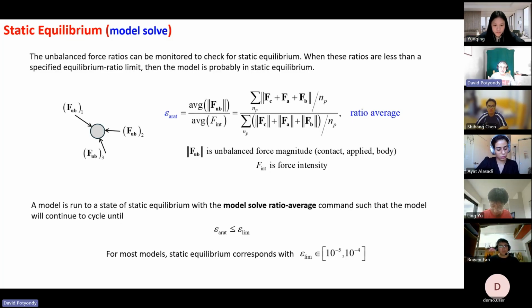And so one of the ways of determining that is just to cycle for a huge number of cycles, and eventually you're going to see that all the velocities are incredibly small, like 1 × 10^-12, because they're just vibrating at this super small value. It's important to know that the velocities will never exactly equal 0, because when we're using a computer, we're using finite precision mathematics.